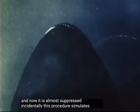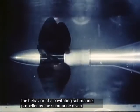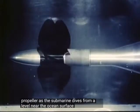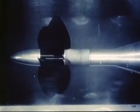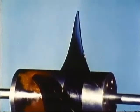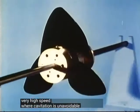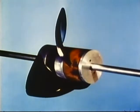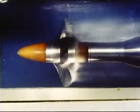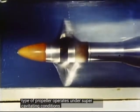Incidentally, this procedure simulates the behavior of a cavitating submarine propeller as the submarine dives from a level near the ocean's surface. This model is typical of a propeller designed for non-cavitating operation. Here is a propeller designed to perform well at very high speed, where cavitation is unavoidable. This type of propeller operates under supercavitating conditions.